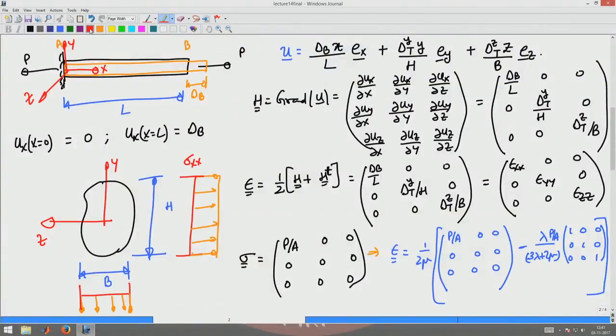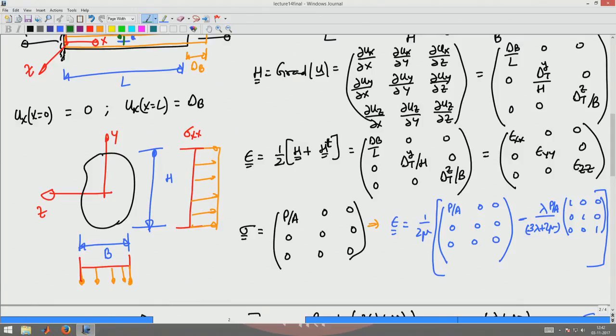We saw what a strain gauge is in the previous lecture. So, what I will do is I will stick a strain gauge here like this, which will give me epsilon xx, and I will stick a strain gauge like this to get me the strain epsilon yy, and I will stick a strain gauge perpendicular to that to get epsilon zz. Okay. So, I can directly use a strain gauge to get these strains, or I can measure it from the displacement that I see in the body.